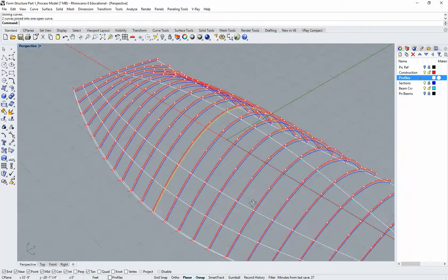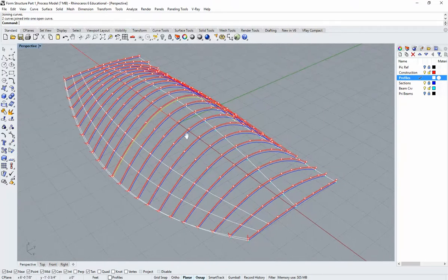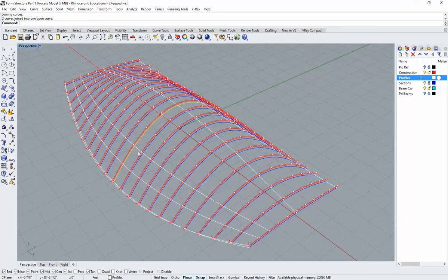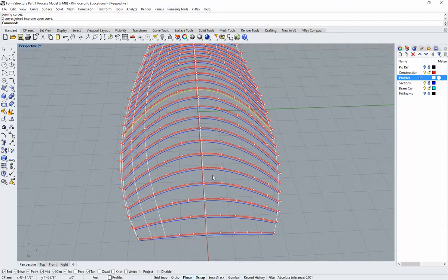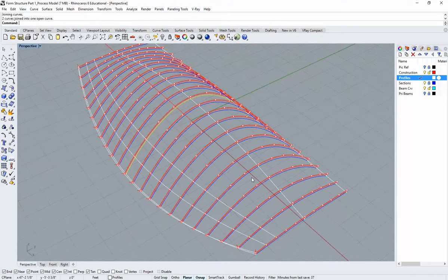All right, go ahead and pause and continue and finish the whole entire structure. So if you modeled just this one quadrant, you can mirror that around to this side. And then you can also mirror the entire side around to that side. I'll show you that in just a second once I get it finished up.